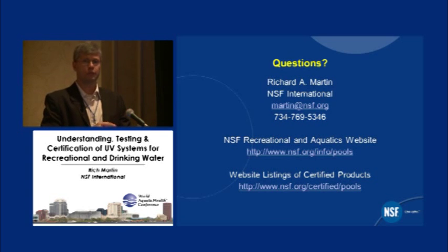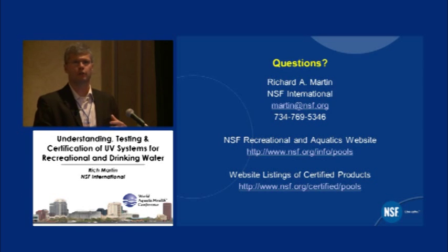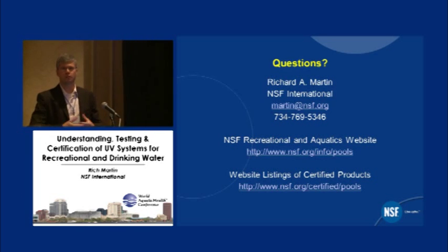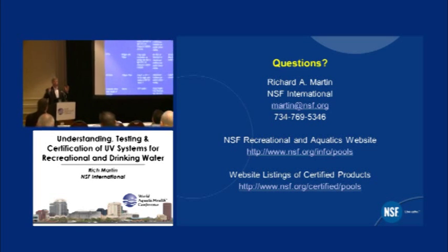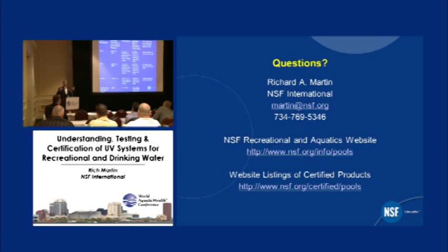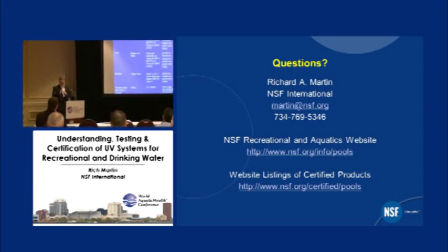So some UV systems have either manual wiper systems or automated wiper systems. And several slides ago, what we're looking to do is actually specify those, along with the cleaning system. What is the UV system? Is it low pressure, medium pressure? Those are basic indicators, in some ways, of performance or energy consumption, but also the potential need. If you've got a really hot medium pressure system, you might have more buildup of either scale or biofilm. It's not directly correlated, but the biofilm will definitely impact transmission.